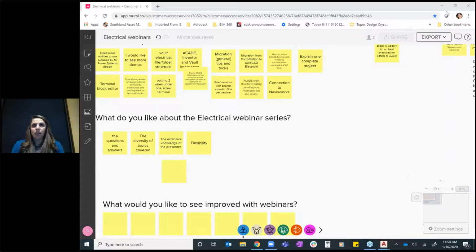To me, that's a network latency issue. We hear about it often, just the way corporate networks are set up sometimes. Having AutoCAD Electrical go out to your corporate network and come back to give you information just causes latency issues, and that's why you're seeing performance problems. Matt's absolutely right, Vault would solve that. I don't know how big you are or what IT requirements you would have around that, but I think that's ultimately your goal.